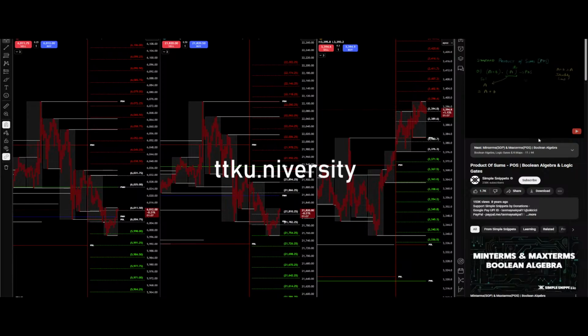wherein we've discussed the Boolean algebraic laws. Okay, so why did I write this a or 0? Now the 0 can be written as b and b complement. Now b and b complement is equal to 0, and this is from the complement law. So as you can see, you need these laws and you need to understand each and every law to solve these numericals. Now applying the distributive law, we get a or b and a or b complement. This is the distributive law.